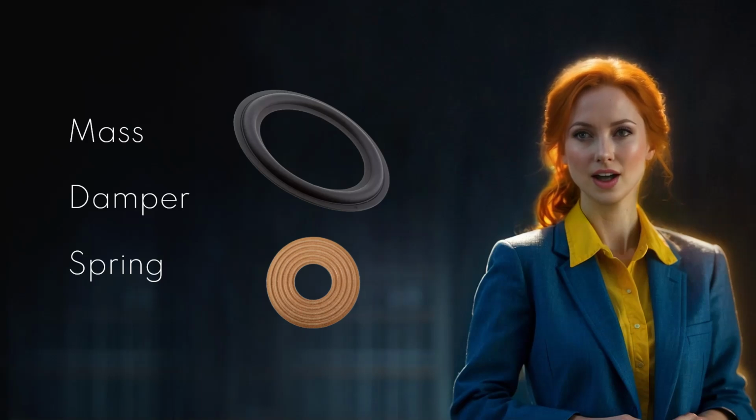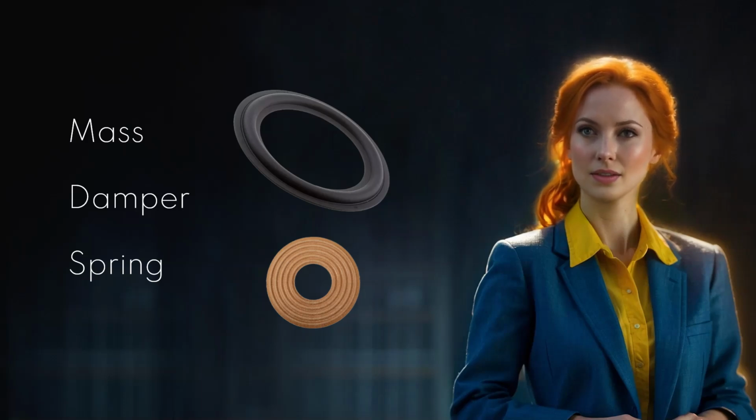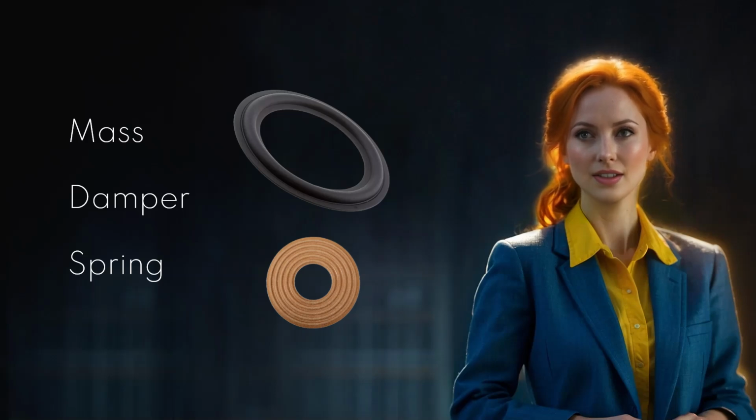The surround is the flexible ring that attaches the outer edge of the speaker cone to the speaker frame. It allows the cone to move back and forth while providing restoring force to center the cone when there is no input signal. The spider is another flexible component located behind the speaker cone, usually closer to the voice coil. It provides additional support to the cone while allowing it to move freely back and forth.